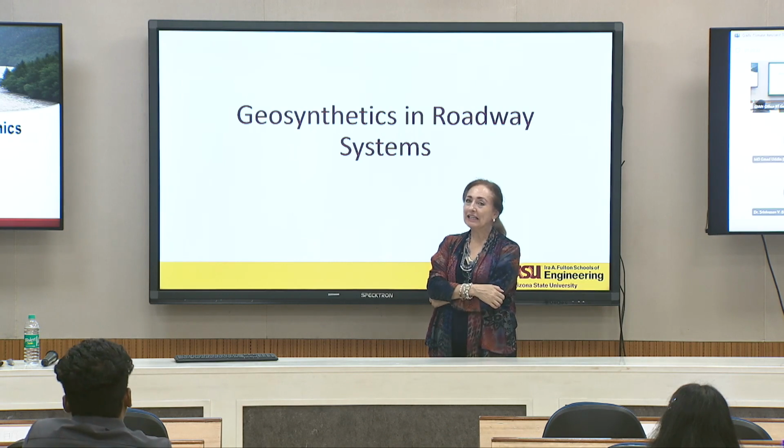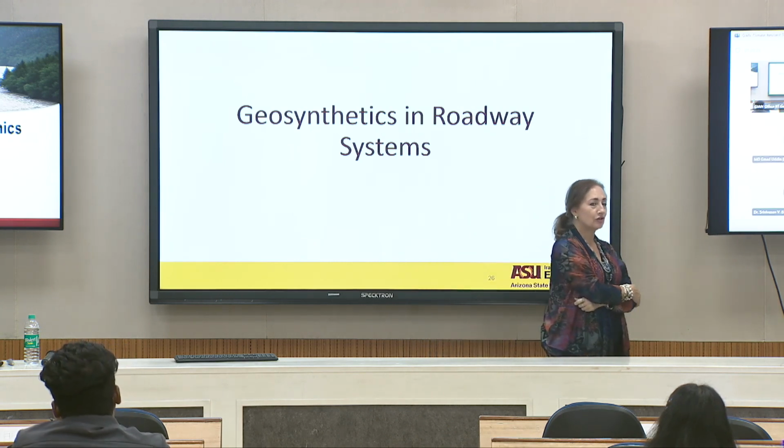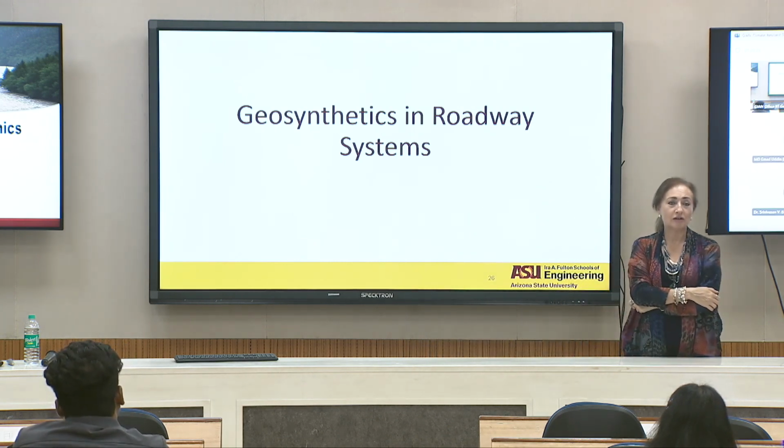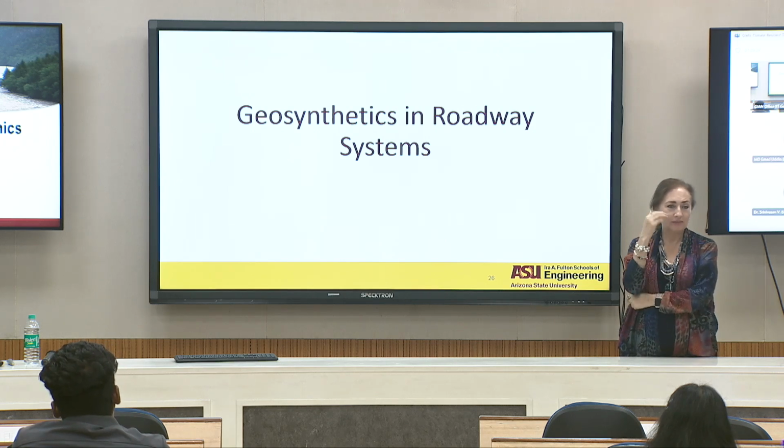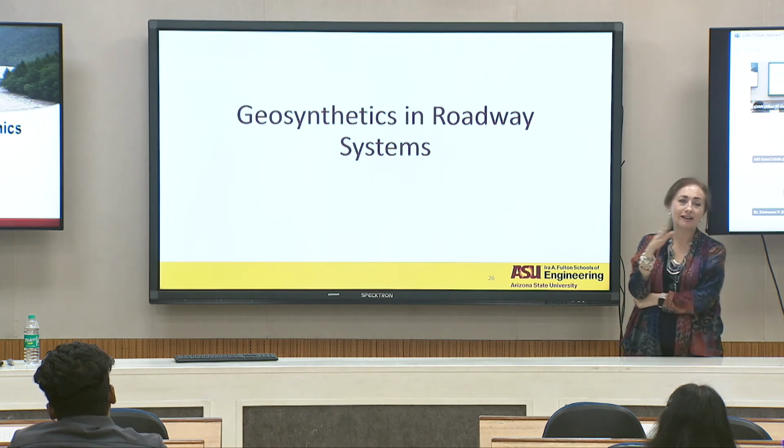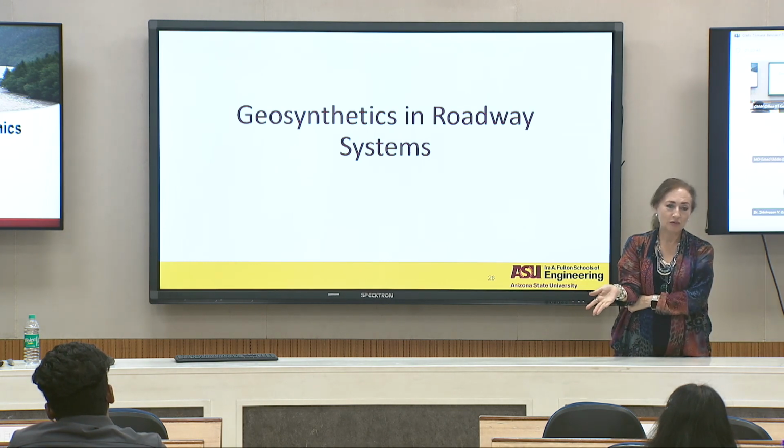Well, I'll have to check, but I'm very sure there are correlations with unconfined compressive strength. DCP, dynamic cone penetrometer, is dynamic, but there are some measurements of strength like CBR, right? So I'm very sure there are ratios that you can get between the unconfined compressive strength and resilient modulus. That's the best we can do on that one.